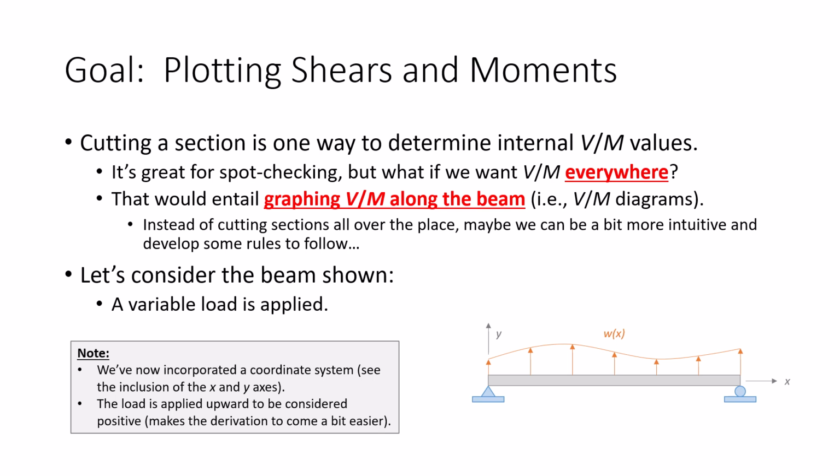If you remember from statics, what is arguably most important when constructing a shear and moment diagram is that you understand the polynomial relationship as it pertains to derivatives and integrals, right? If you have a line and you integrate it, you get a parabola. You take a parabola, you integrate it, you get a cubic function, etc. Those integral and derivative relationships are critical in developing a means of constructing shear and moment diagrams.